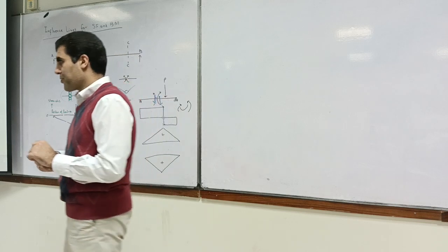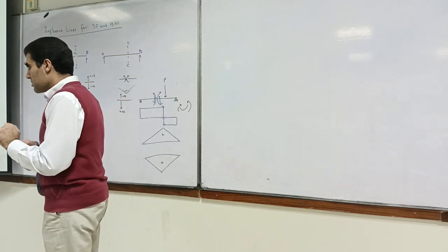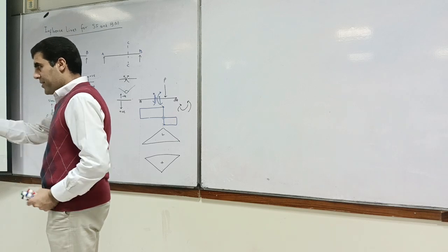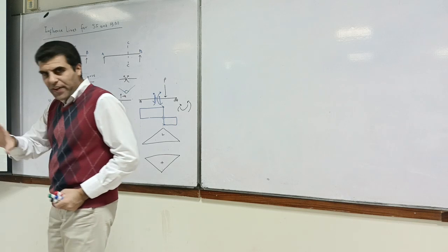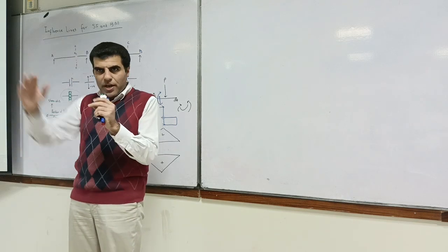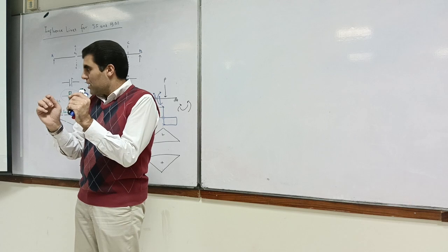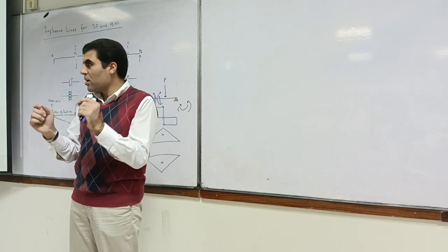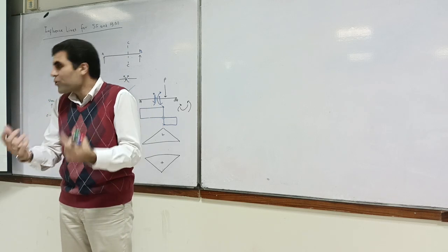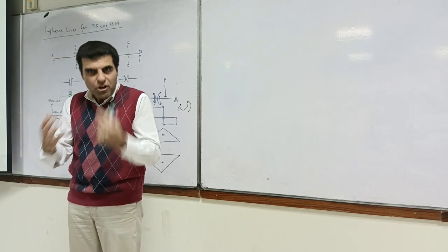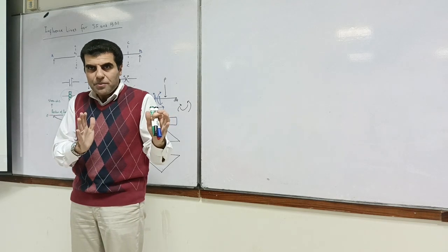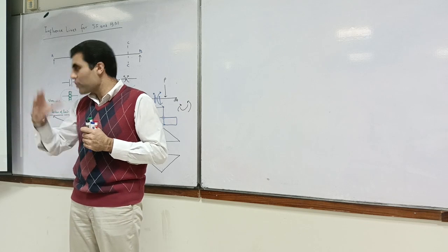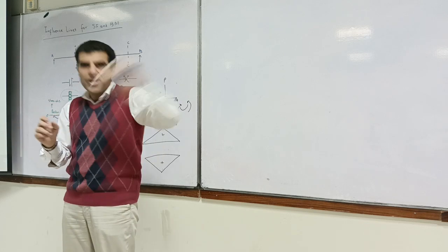What if the maximum shear lies between the points? For example, if we divide into 6 intervals, you will get the trend, obviously. If your maximum shear comes out to be in the middle of two points whose shear force you have already found, and it is not exactly on those points, then you will find it out eventually by studying the trend.